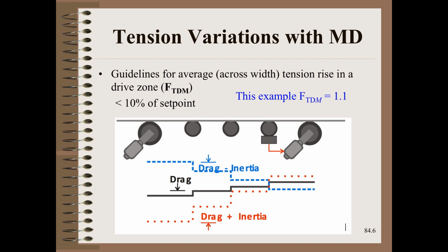Tensions measured at a load cell define tension only at that roller. Tension on the roller just upstream and just downstream will be different, even if they are all in the same drive zone. At steady state, this is largely caused by roller bearing drag. Also, this downweb tension profile will be different during acceleration, run, and deceleration.